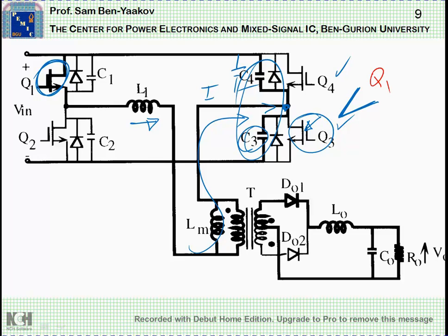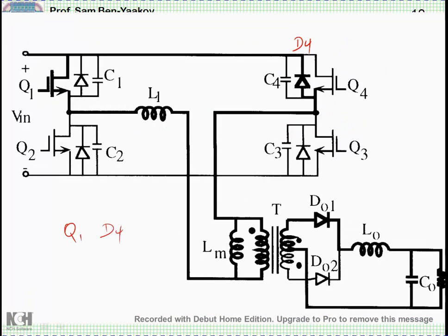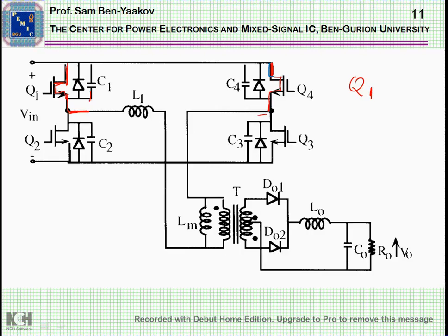So what happens is that this voltage goes up and up and up, and eventually it will hit the point that the diode will conduct. So we actually cause, by this inductor, a self-commutation, bringing this voltage back up to here. Now we can turn on the transistor.